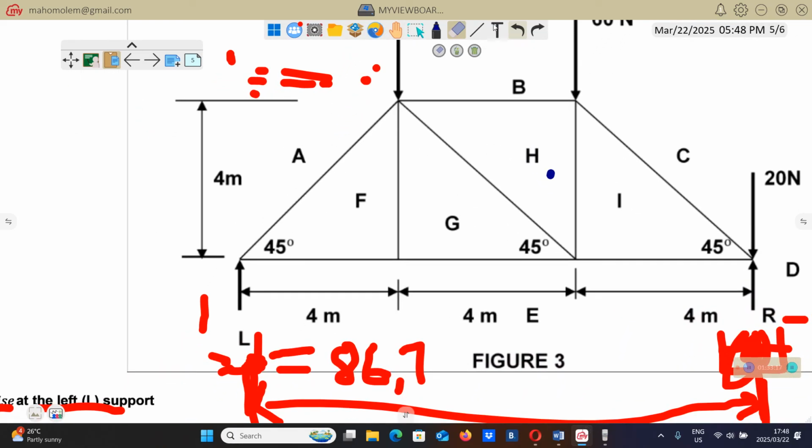Like here, you will have this one and this one and this one. You will have three. You can say three forces or three members. You can start there. It's unlike here. Here at this joint, at this point here, you'll have one, this line, two, three, four. You have about four lines or four members. So here you'll have one, two, three. Okay, it's fine. Let's start where you have less members. But as I've said, you can start at any point. You are not forced to start there. If you want to, you can still start with this joint here.